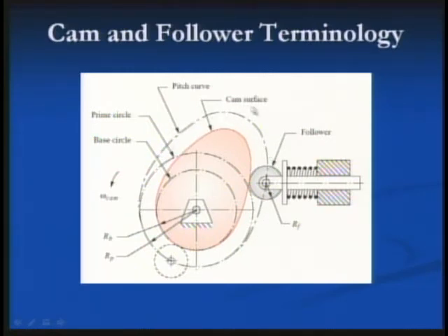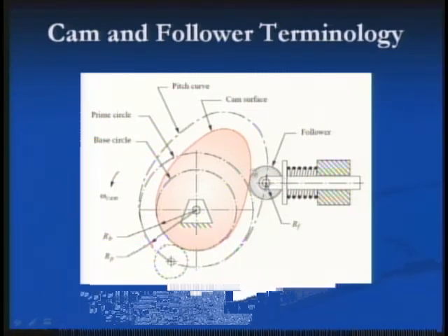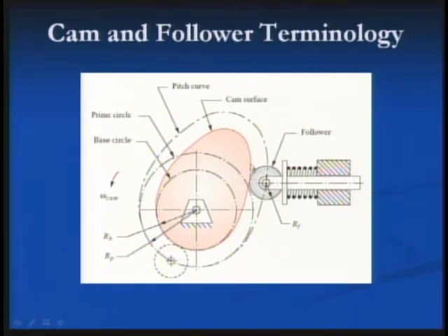And we're going to create that kinematic cam in a moment in Dynacam. If you, again, had the physical cutter chewing away the metal, you would generate this cam surface. The smallest part of that cam surface is called the base circle right here. That's the circle that I can draw within it without going out of the cam physically at any point. And its correspondent in the case of the pitch curve is called the prime circle. So it's the prime circle that we're going to choose in order to determine our ultimate cam size. And around that prime circle, we're going to wrap the S diagram.